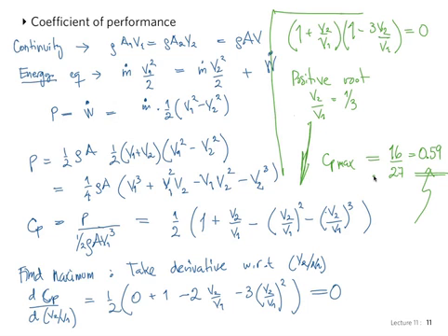The reason for this limit basically is that since the fluid is going to the turbine and needs to slow down on the other side of the turbine, for conservation of mass, if you consider a stream tube, the area has to get bigger. And so, going forward in front of the turbine, the actual amount of wind that the turbine is able to capture is smaller than the area of the full span of the rotor. The other way around: the inlet is smaller than the outlet because the fluid needs to slow down. So for conservation of mass, the area must be bigger. And so in front, the amount of wind that the turbine can catch is a smaller area than its own span. Does that make sense? Makes sense.